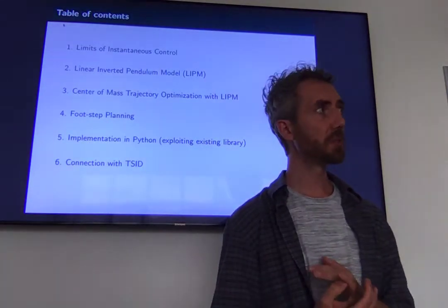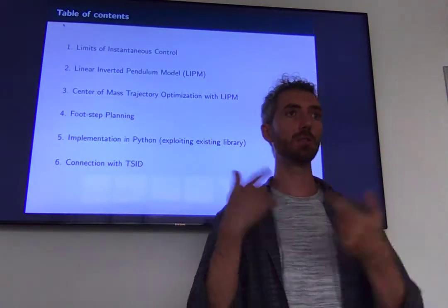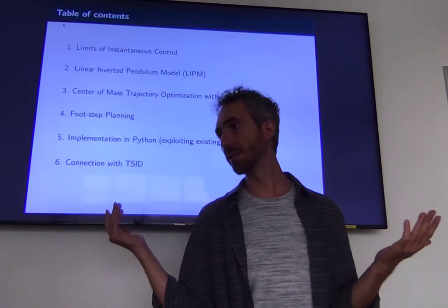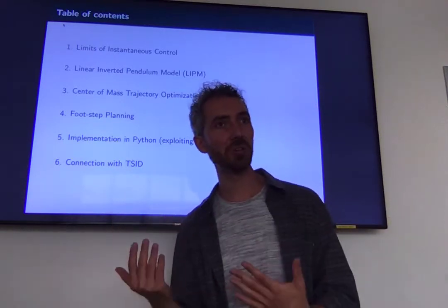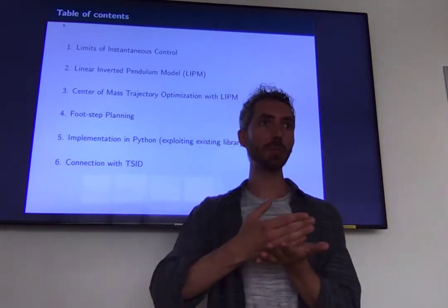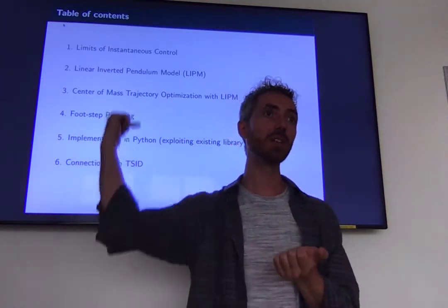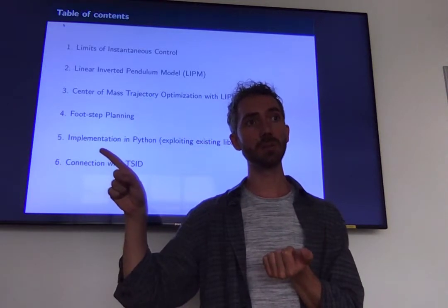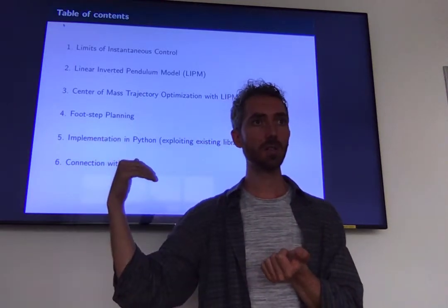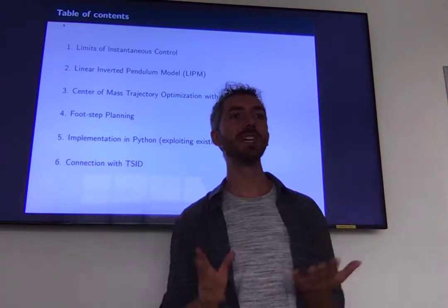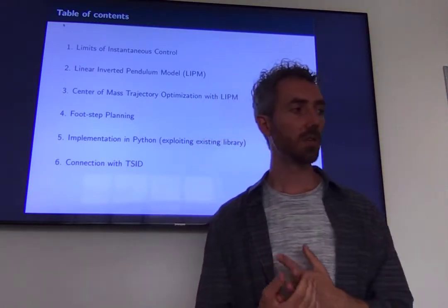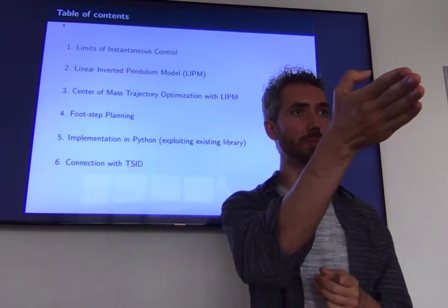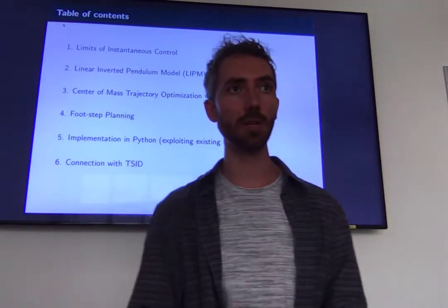Yeah, you can see MPC as trajectory optimization recursively iterated, or you could see it as the online computation of a control policy, because the control you get at each time step depends on the state, because you re-solve the whole optimization problem with the new initial state, which is your current estimation. Okay. Yeah, I mean that's just a point of view, if you consider it as a closed loop or an open loop. Yeah, but the problem you solve is open loop, so there is no discussion about that.